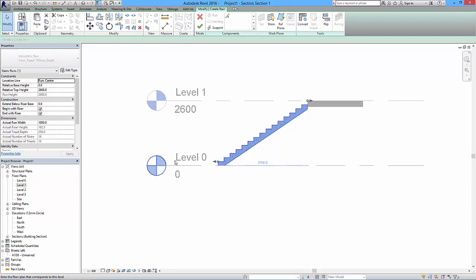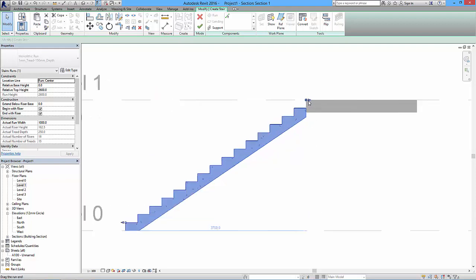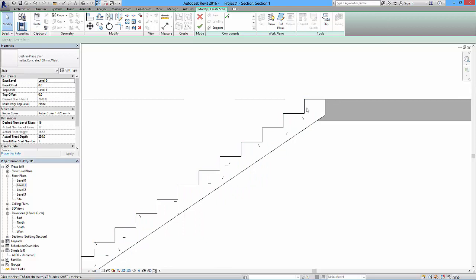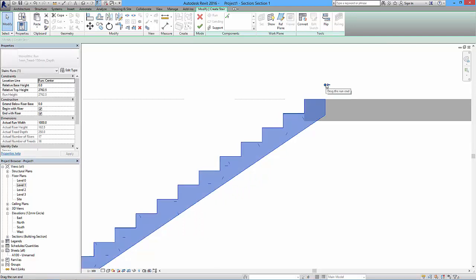So this one is going to move it, but this one is going to do a different thing. And similarly, this one's going to move it, and this one. Notice it's sitting at this point. So as far as the stairs are concerned, it's all working nicely. If I decided I wanted this to be at this height, then I could just drag this thing to create an extra step. Okay, so that's going to drag that out, but this bubble is still sitting above it. Even though the stairs is lined up nicely, the bubble sits above it. So I'm going to drag that back.